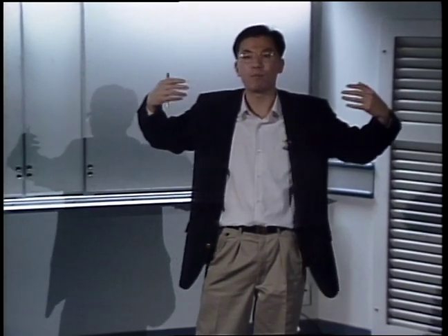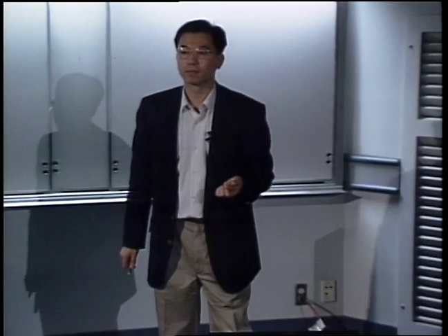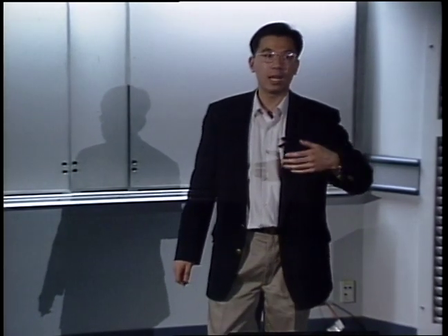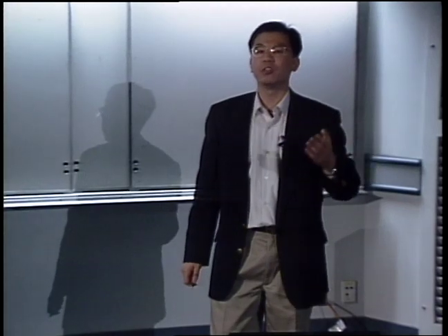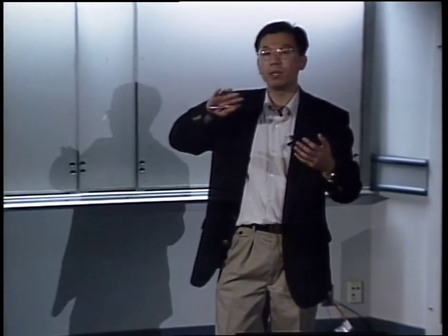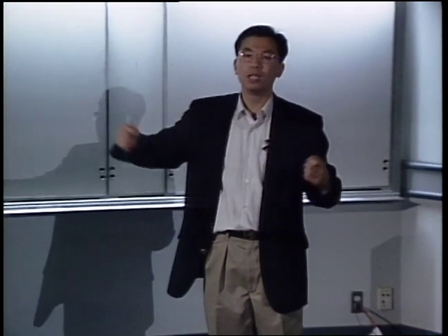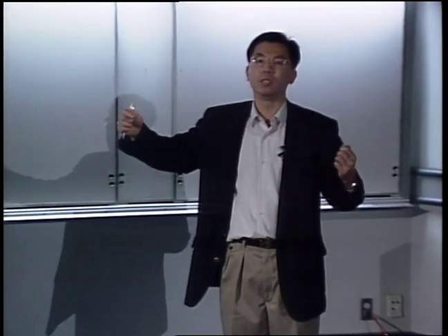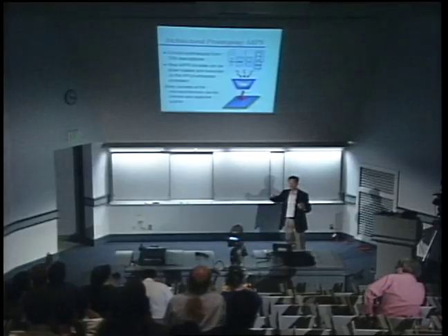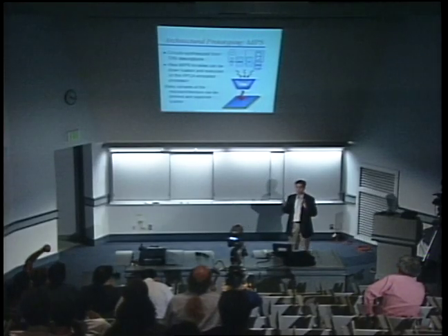Those are set policies. So you preset the clock cycle first? No, we map and then we synthesize. Right now, we don't try to meet a particular timing budget. We're now looking at more advanced methodology, because to change the timing, you have to go in and spread a rule over multiple clock cycles, and there are more complicated transformations you have to do. We're looking at that right now, but my compiler doesn't do that. My compiler just does a straightforward mapping.